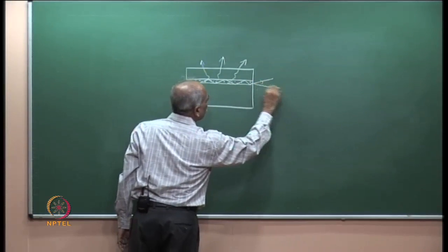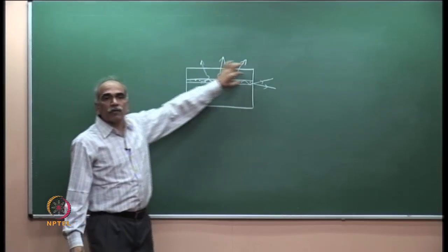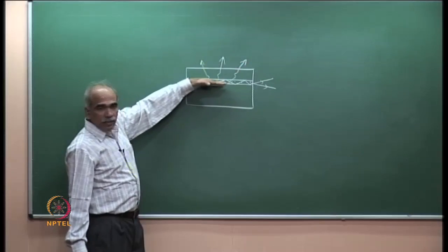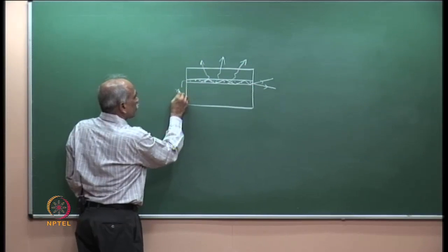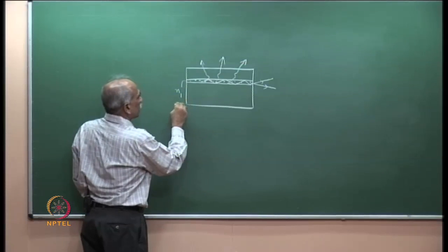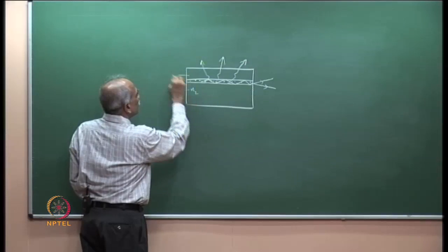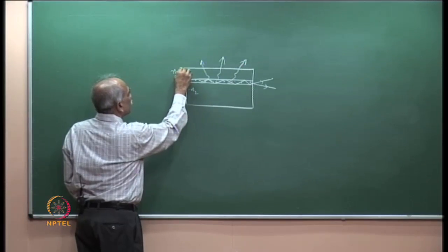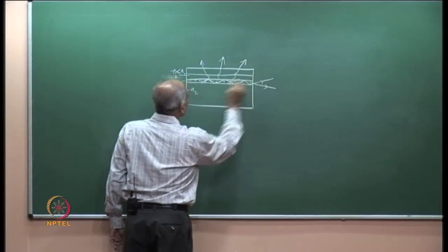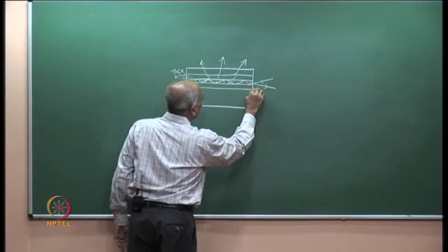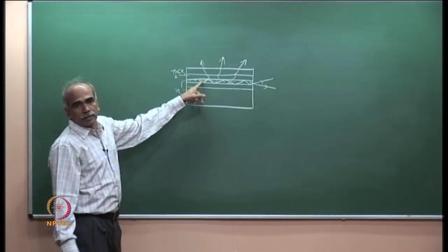The optical confinement is because this material is a lower band gap material, therefore the refractive index N1 here is higher compared to the cladding layers, which have a little lower refractive index, N2 less than N1. Recall that they are high band gap materials on the side because we formed double heterostructures. So these are the cladding materials, this is the active material.